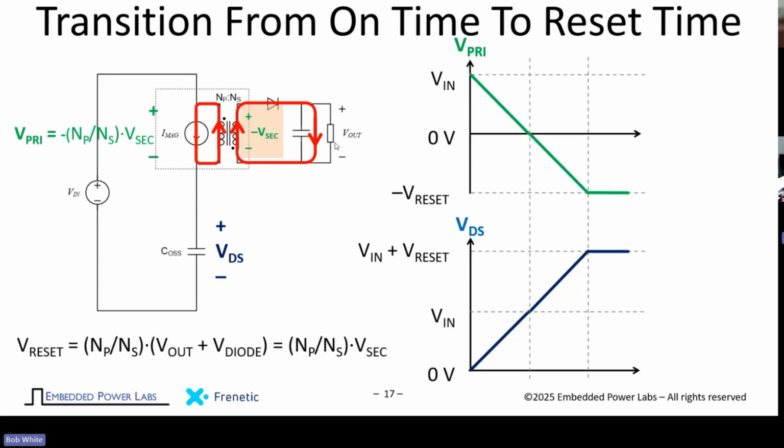And so the drain voltage is clamped, and the voltage across the magnetizing inductance is clamped. We are now delivering the energy that was stored in the magnetizing inductance, the flux that's in the core, to the secondary, and the voltage here is constant. So this is the turn off without leakage inductance.